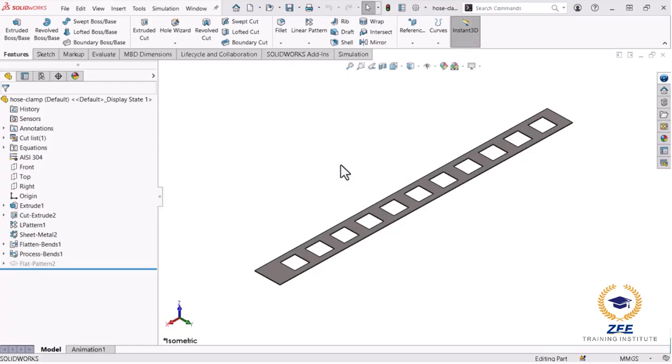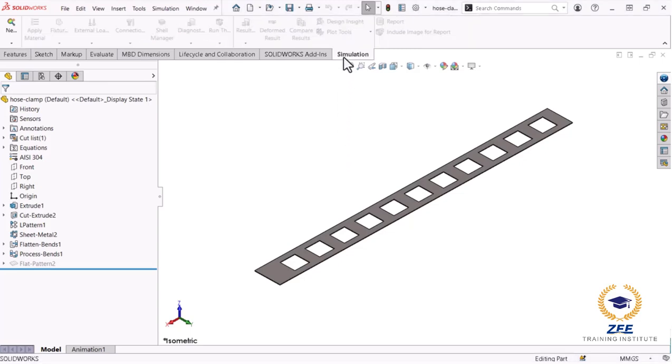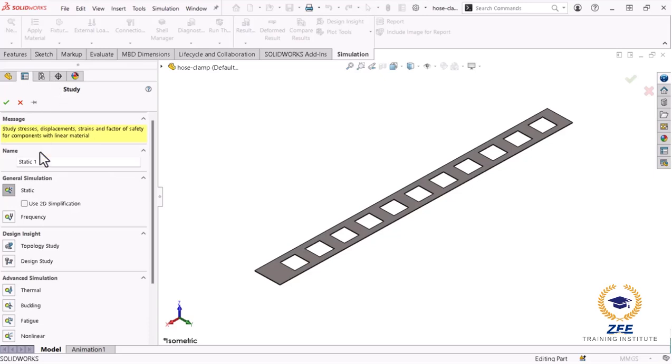The lesson assumes you have a basic understanding of the SolidWorks Simulation linear static module. In general, it is always good practice to start any simulation with a linear analysis. For this reason, I will start by defining a linear static study. I will browse the Command Manager Simulation tab and click New Study. I will keep the static module selected, name the study linear and click OK.